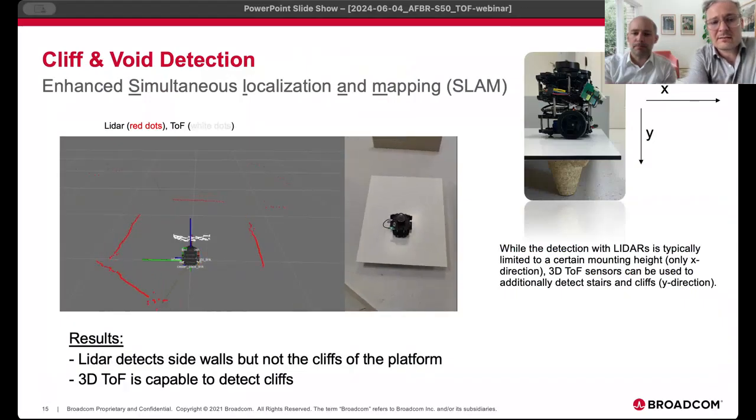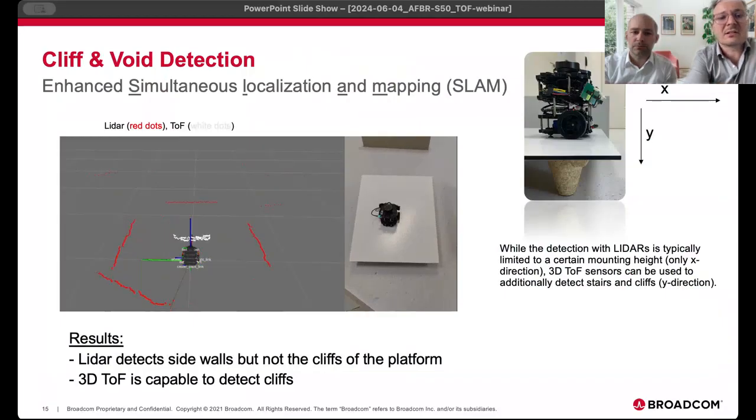If you again look at the video, this is a ROS implementation for Robot Operating System, which shows the live sensor data of the TOF devices looking downwards to detect the cliff. You can see here that whenever the cliff is detected, one of the sensors actually shows a moving structure of white dots, which gives you the indication that the cliff is detected properly. This form of sensor fusion can be really beneficial to AMR manufacturers or even AMR users.